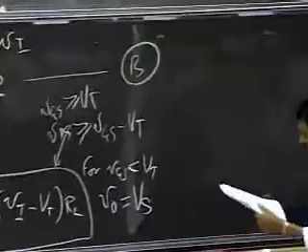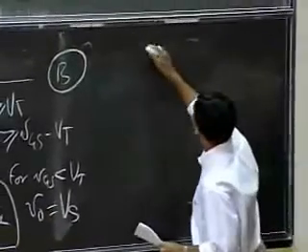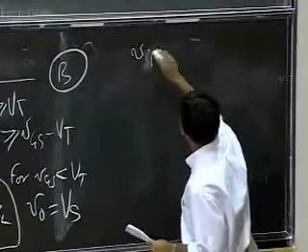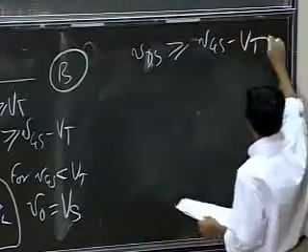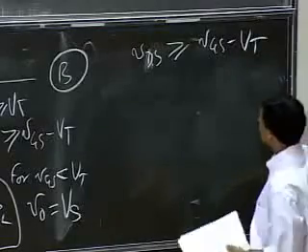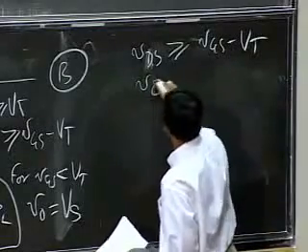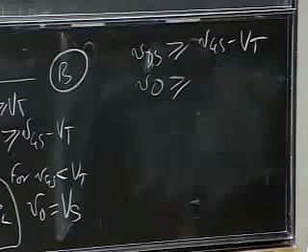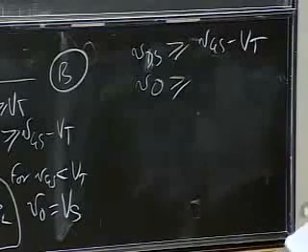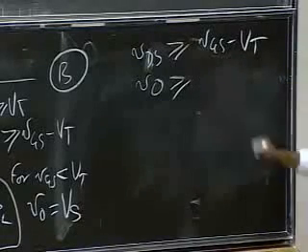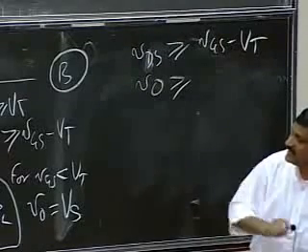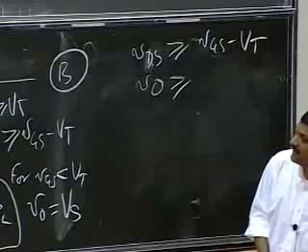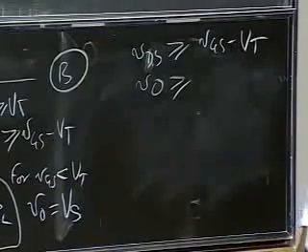I'd like to stare at this constraint with you for a second. VDS greater than or equal to VGS minus VT here, and VDS is simply V naught. I want to rewrite this constraint in terms of IDS. It will come in handy. IDS is K divided by 2 times (VI minus VT) whole squared.